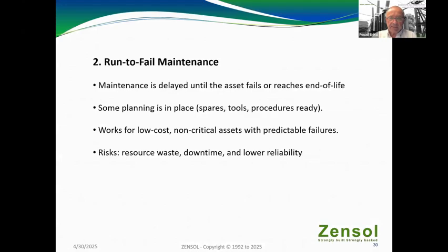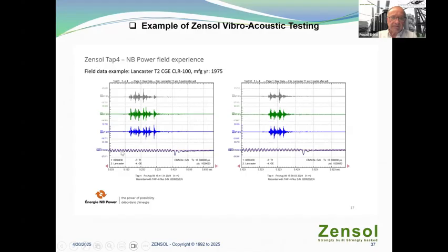No, I think it's at the end. Do you see here? Yep. On the left, you have the motor current. The motor current ends here, and here you have the vibroacoustic phase A, B, and C. And here you have the same, but this one's from 1 to 2, and this one is 2 to 1. And they must be identical.